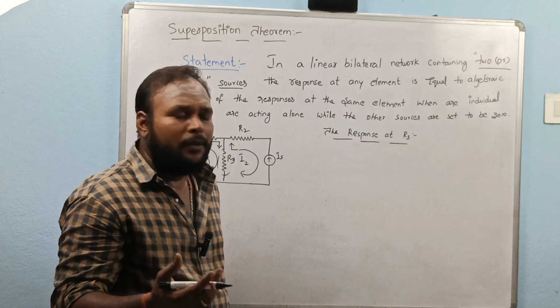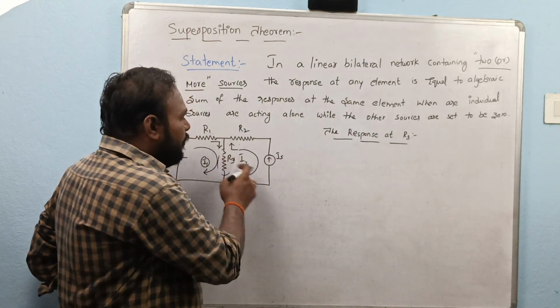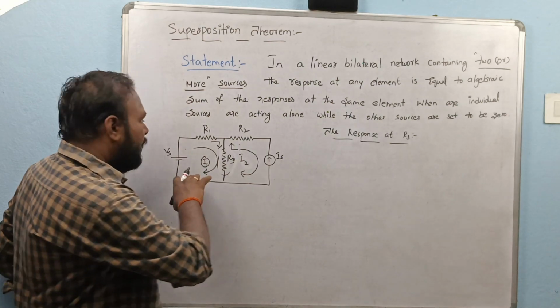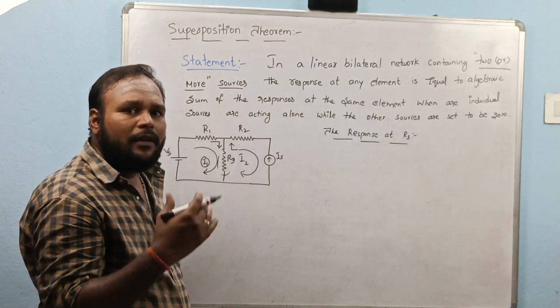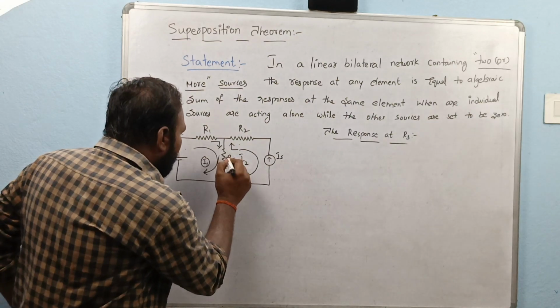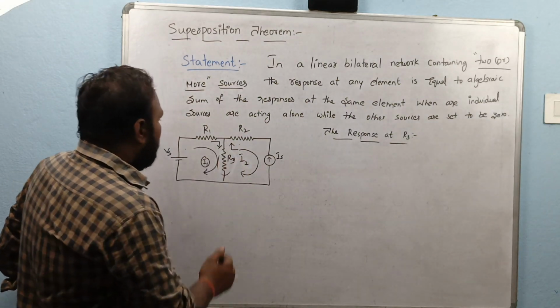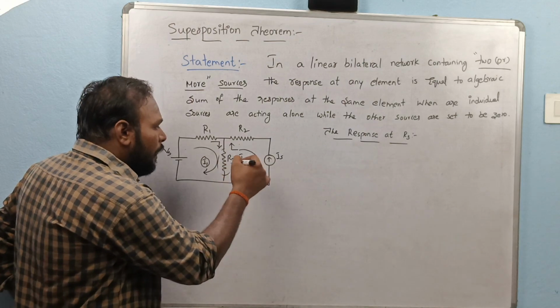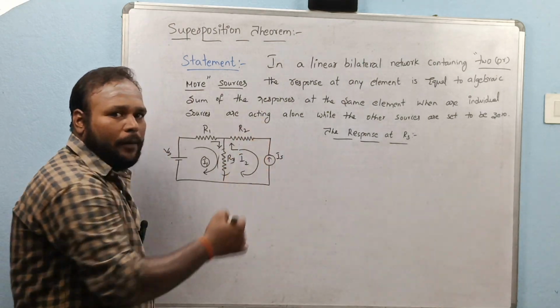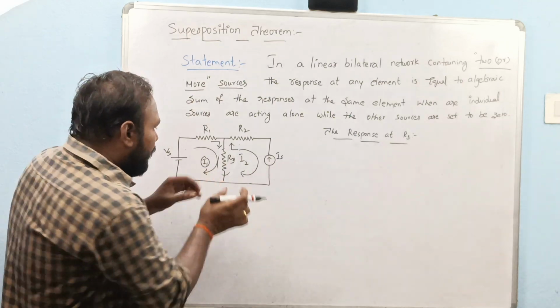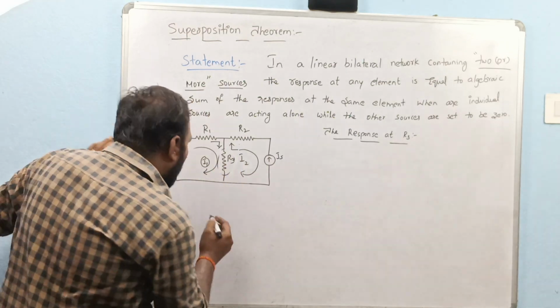If you take it according to the direction of the current source, it should be anti-clockwise, but I take the current direction in both loops as clockwise. It's not a problem. Now the current in loop 1 is from top to bottom and in loop 2 is from bottom to top. That is, both currents are in opposite directions when considering the resistor R3.